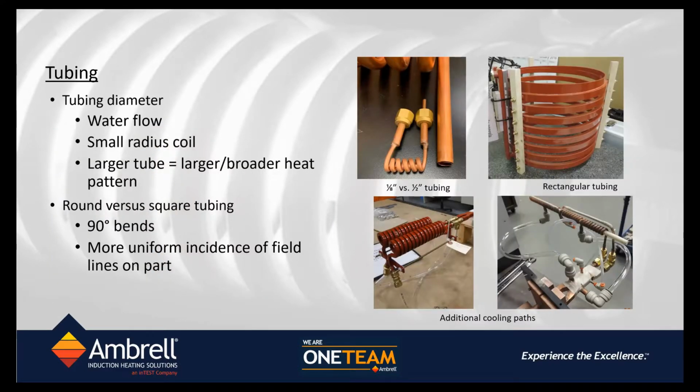Well, then once you determine what shape of coil you need, you have to determine what size copper tube to use. If you go to a regular hardware store or go online to look for copper tubing, you will find that copper tubing comes in all different shapes and sizes. You can find round copper tube, rectangular copper tube, square copper tube. Well, when do you use which? In a lot of cases, the number of turns that you have to fit in an area or in a length determines what shape of copper you use.